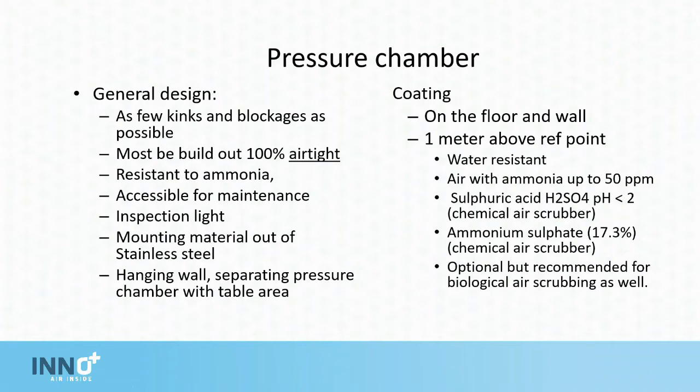To protect the pressure chamber, coating should be applied. The coating must be applied to the walls and floors. On the walls, with a minimum height of 1 meter, and the coating must be waterproof. The coating should also be resistant to 50 ppm of ammonia.